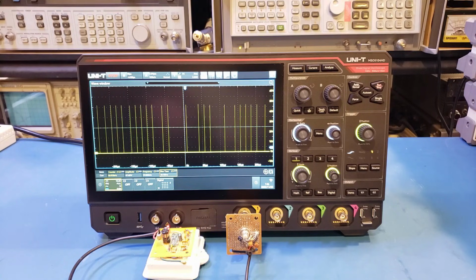The MSO5104HD can handle a maximum of 400,000 segments. So while in this case each segment is just slightly bigger than 1 kilobyte, the segment is guaranteed to contain meaningful data. Of course, you can adjust the number of segments based on the signal complexity.